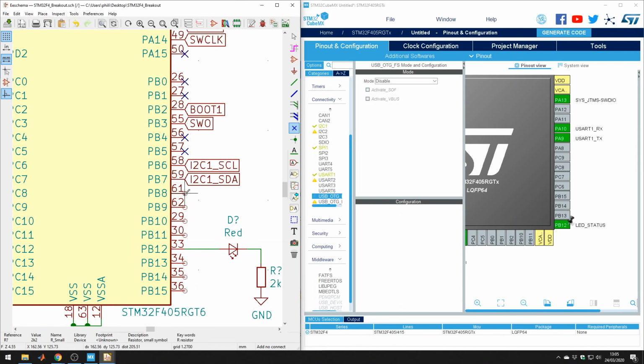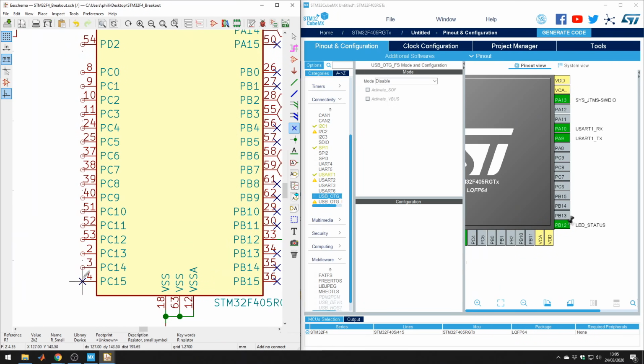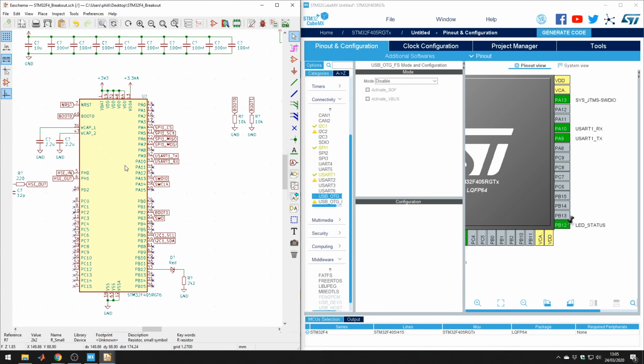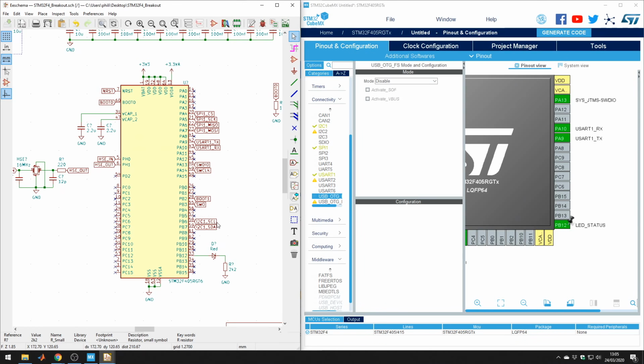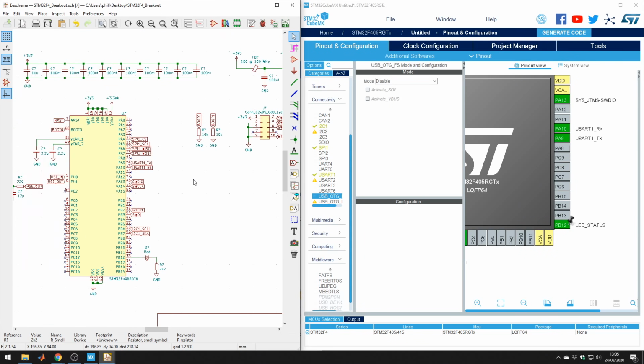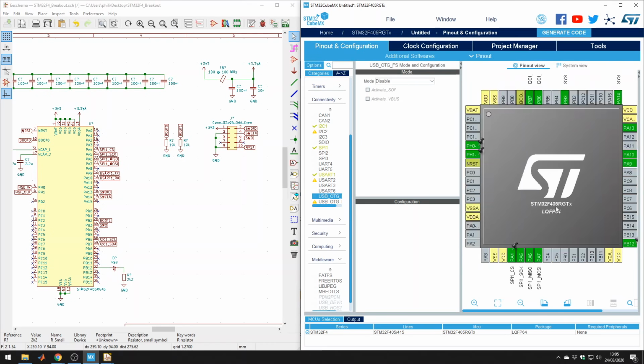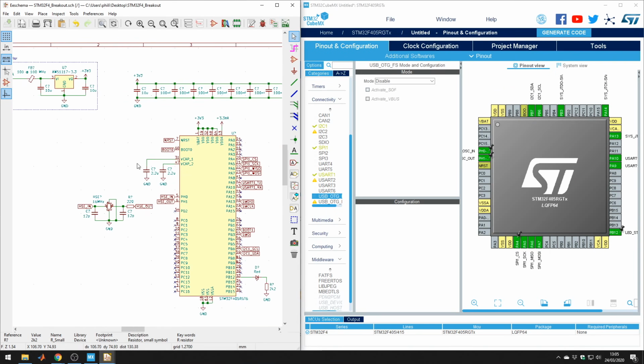Okay, on to this side, using these no connect symbols. Oops. And on this side, feel free to fast forward this bit as well. Almost done. Okay, so now we've pretty much got everything hooked up: SPI, UART, serial wire debug, the boot pins, the reset pins, the crystal, caps, SCL. I'm just checking everything. And of course you want to take your time when checking the circuit just to make sure everything's correct, because you can waste a lot of money redoing circuits, especially with the PCBs.